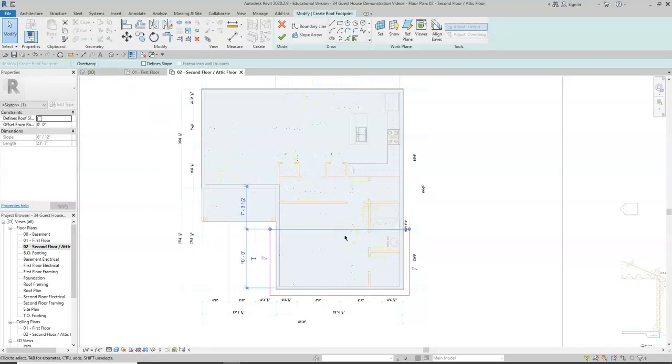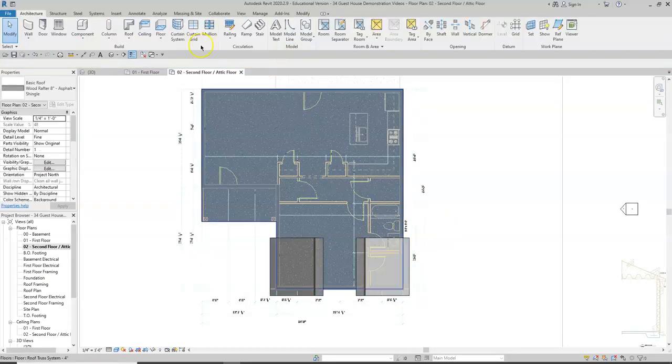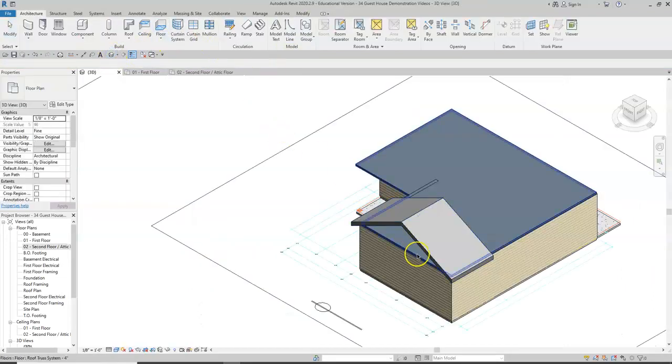Now that I'm thinking about the actual design part, we're going to keep that line way down here. So go ahead and move it down. If it's way up here, just move it down and make sure you have 4 sides connected. We'll click the green check, and boom, there's our roof. 3D view, there it is. All right, we have a gable roof, slope 1, slope 2.